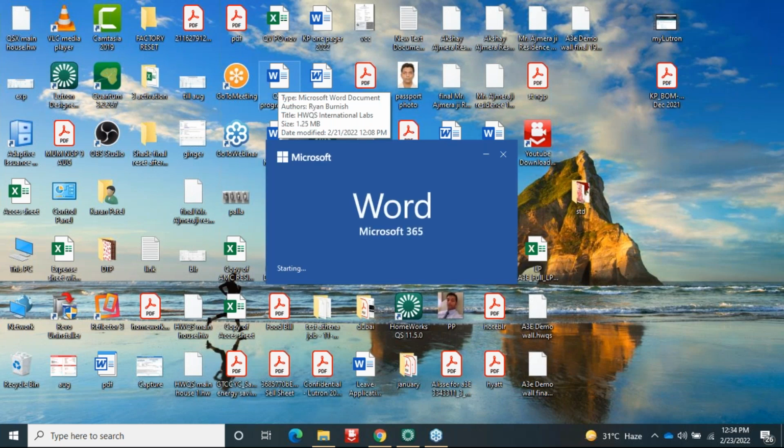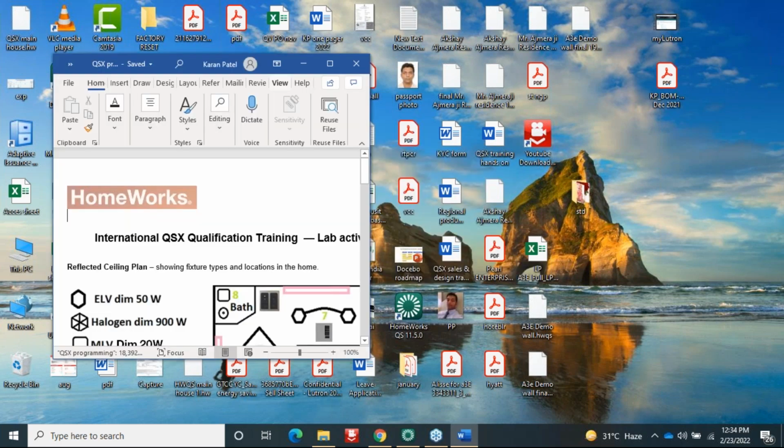Why is it important? Because it acts as a product filter for that country, and the RF frequency and the time clock events are based on the country location. So these are the three important things, so the country name is very important. And once you define the country name, it cannot be changed later, so you have to be very careful while choosing the country.